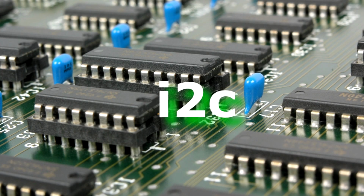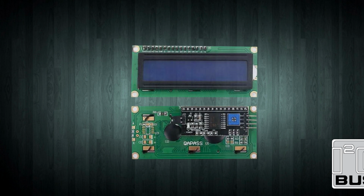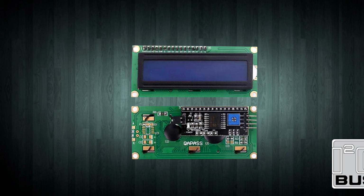Yes, my dear friend, in this lesson we will learn about I2C. It's especially important that we know the structure of the I2C protocol, because there is an I2C module on the LCD screen we will use. I2C is a Serial Communication Protocol. Communication takes place over 2 lines. These are SDA and SCL. Both buses are bidirectional. That is, data can be sent and received.